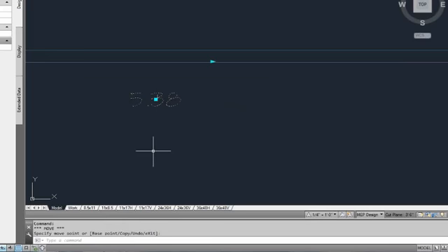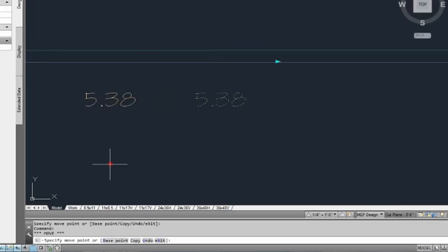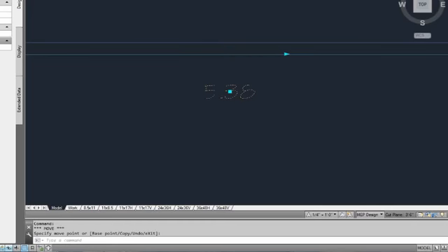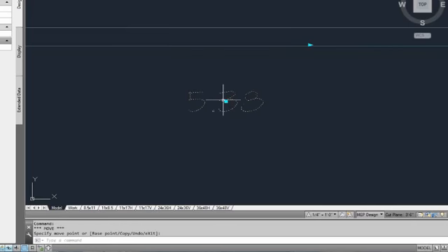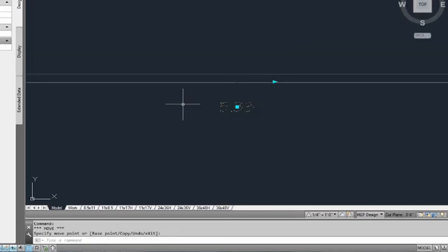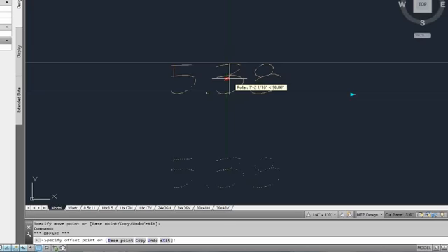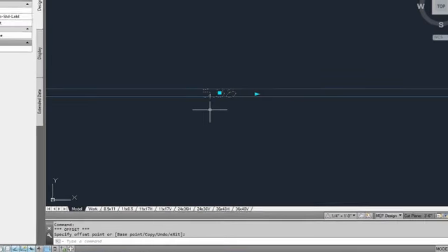But if I try to move it down again, it will not move anywhere. If I hover over that label once again and choose Move, all it's going to do then is just move its direction. So as I mentioned before, labels are a little bit more difficult to get placed exactly where you want them if you don't want them placed exactly onto the pipe. A label's purpose is to basically live on the pipe or very close to. So that's what it's always going to try to do.